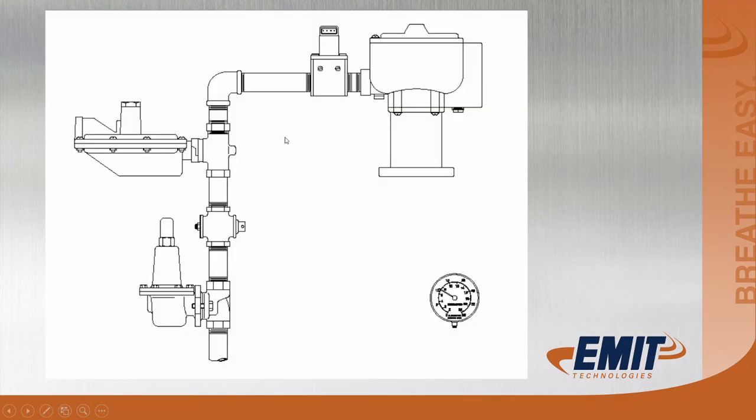Okay, let's set up a fuel system for a natural gas, non-turbocharged or naturally aspirated unit. First, you want to start out, you want to open your stepper motor up. Our range on the stepper motor is 500 steps to 0 steps. 0 is closed, 500 is open. Okay, we're going to put that valve about halfway at 250 steps.